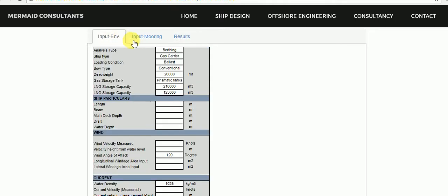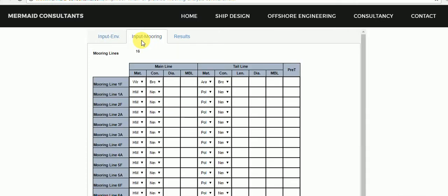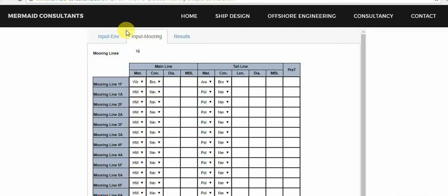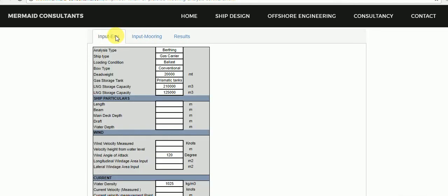Shipmoor is a simple but extensive spreadsheet-based program, using the formulae recommended by OCIMF and UFC, which is very user-friendly for crew and non-technical persons. Shipmoor describes vessels' mooring arrangement and the placement of terminal mooring bollards. Locations are prepared on simple spreadsheets. The wind and current velocities and directions are then input to analyze planned mooring system by using Newton-Raphson approximation method. Lines that are loaded more than their safety limits are highlighted in red.